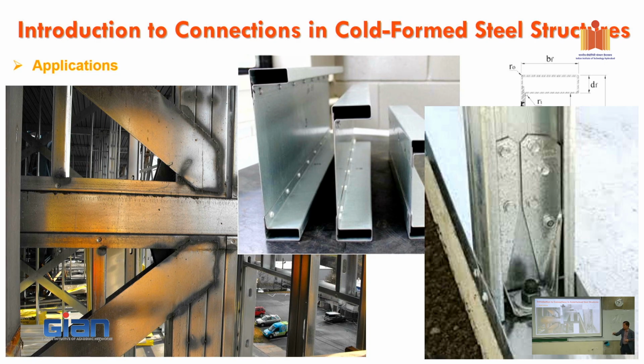So the one that I talked to you about from Australia, first we used cold form steel thick one, but it's not going to work. When we tested that one, it just lifted up, and there's a big gap in here. So it failed in this connection, not in the shear wall. So that's why we have to replace this one by using 10 millimeter hot roll steel. We have to make our own one. And that's just something to share with you, the challenge. Yes?